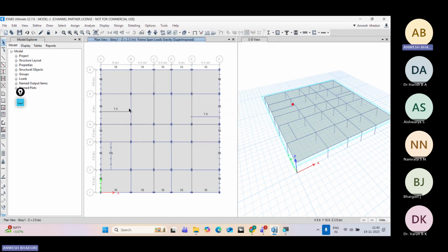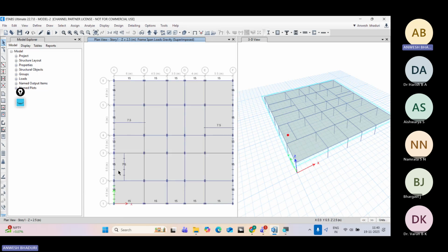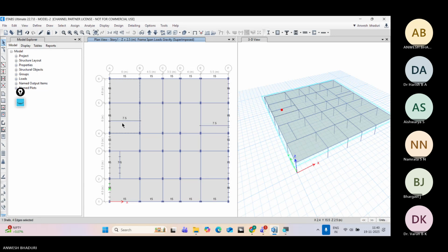Now, due to the addition of secondary beams in these panels, your load distribution will be primarily one way. Right. So you can define your membrane having a one-way load distribution, and you can instruct the program to distribute the loads accordingly.